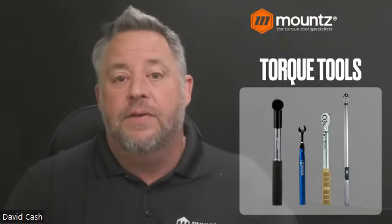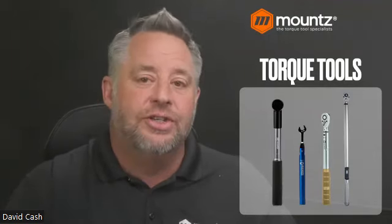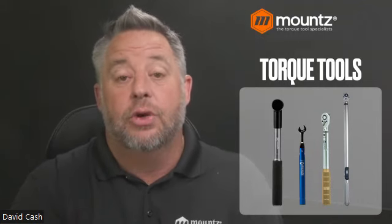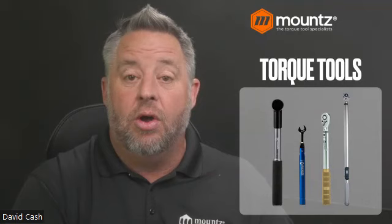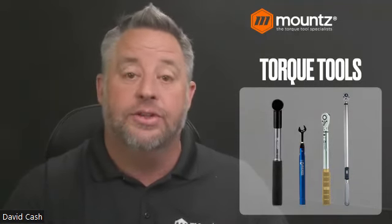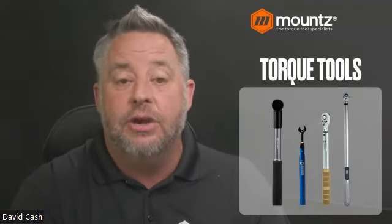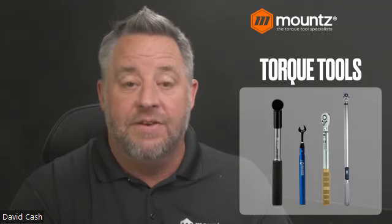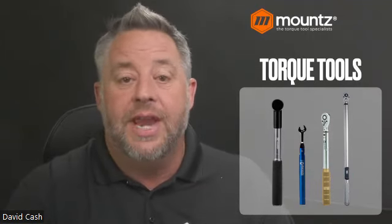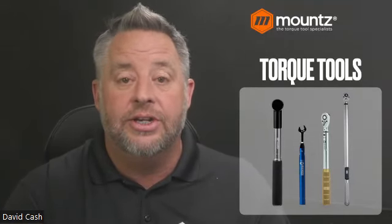The next type of torque tool that we are going to be talking about is torque wrenches. There are a number of different styles of torque wrenches, and they primarily all work on the same function that we talked about with the screwdrivers. We're compressing a spring to a certain value, and that gives us our torque value. With the different drivers that we have here, starting on the left is a cam over style of wrench.